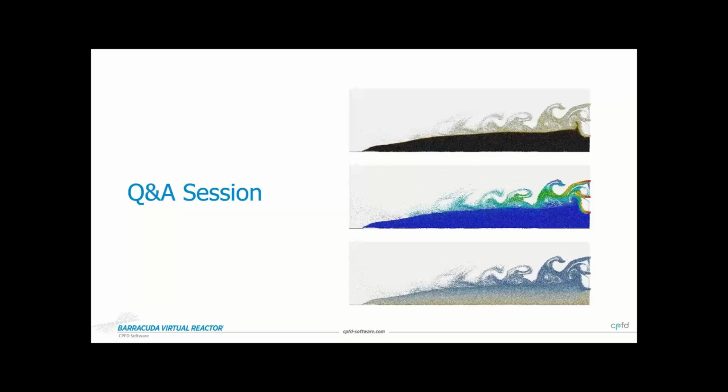I could color my 40/70 mesh blue and the 100 mesh red, and they will show you where these particles are settling. I can also block regions, or block one particular size from being visualized and view only one set. These are commonly used post-processing tricks with Barracuda, and the same can be applied for this problem as well.